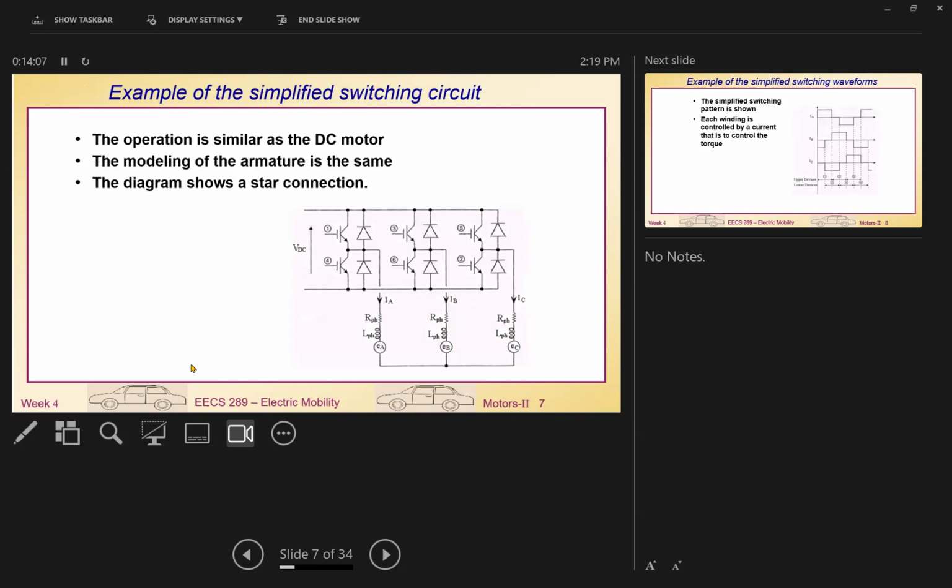So that's how it looks like. Typically you can see that this motor still basically looks like a DC motor. It's a DC motor anyway, but it's just putting the motor inside out. Before, in the DC motor, the PM is outside, the winding is inside, and there is the commutator. But now we flip it inside out, the outside becomes the winding, and the inside becomes the PM. So they do it the other way. That means each phase still has some winding resistance and also has its own back EMF. So the motor equation is the same as the DC motor equation, exactly the same.